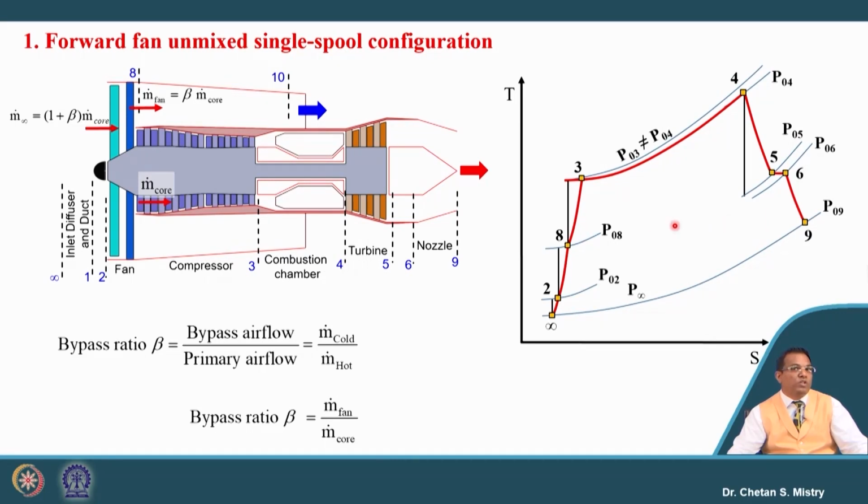Now, let me ask you a question here. We have one nozzle, that is what is with the core engine. We have a second nozzle, that is what is with my fan. So, here if you look at my fan, that will be having exit pressure as 0.8, and the exit condition from our nozzle is nothing but this 10. Okay. So, how do we represent this expansion which is happening inside the nozzle? Any guess? Can you represent process 8 to 10? Okay. Let us see.